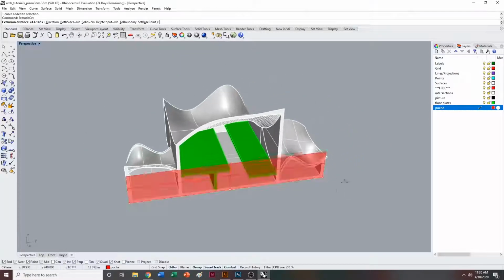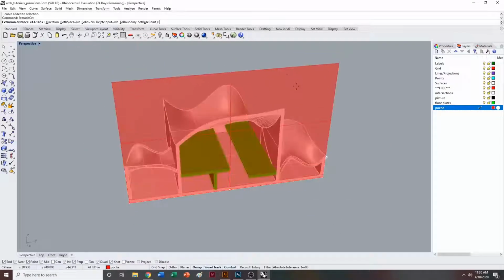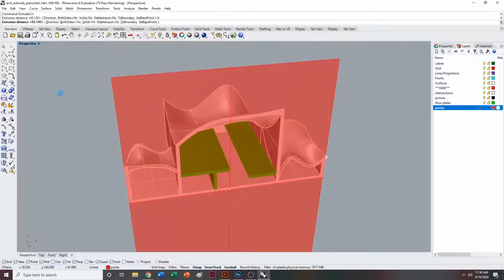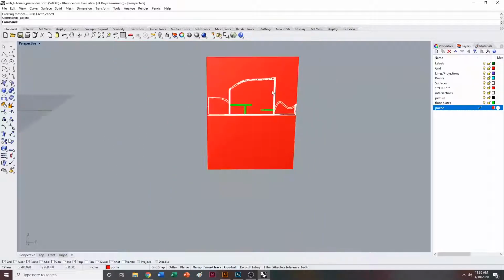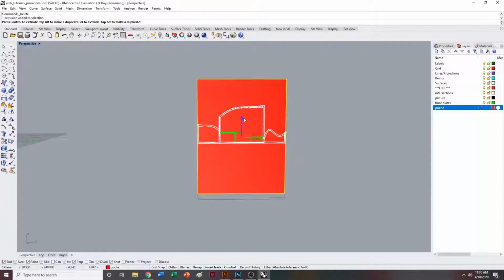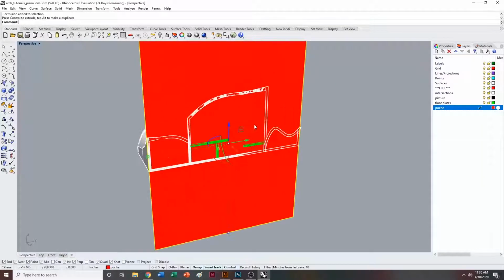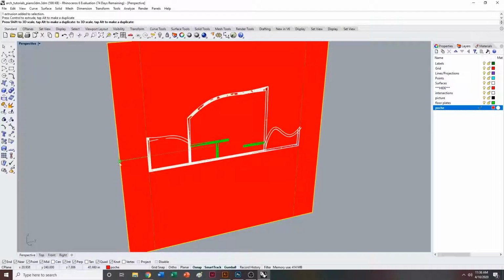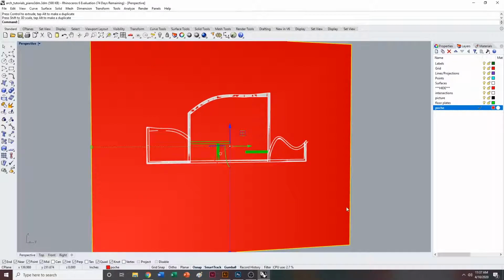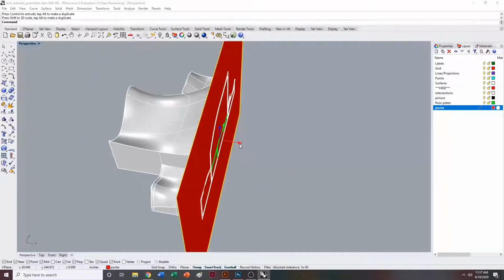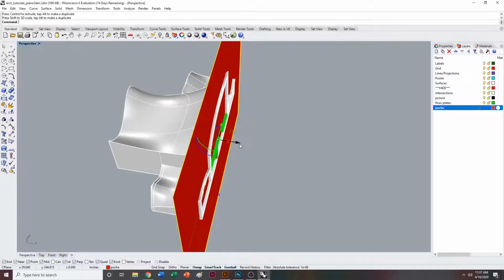And what that's going to do is, of course, allow me to extrude that line in a single direction and make a plane. I'm going to go ahead and hit both sides equals yes. If that option doesn't show up, you can simply hit B and then enter. And basically I just want to make sure that the surface covers the entire object, or surfaces that we've made so far. Again, I'm going to go ahead and make sure that this is wider than this. So basically this project will be centered in the middle of this plane. And I'm going to move it back 1 inch.